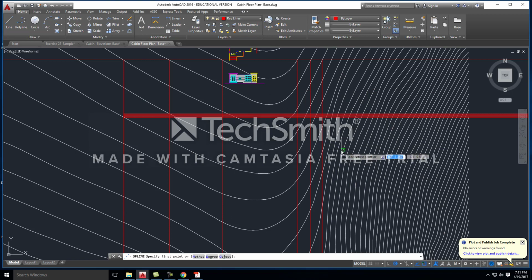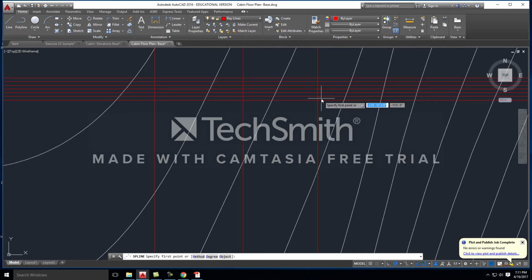So from here, we're going to start at our first line at the lowest point of our elevation, which is right here. I'm going to click once, and I'm going to start to click on the intersections of points for each consecutive line. So we're starting here at the bottom. With my spline curve tool activated, I'm going to click on each consecutive point.